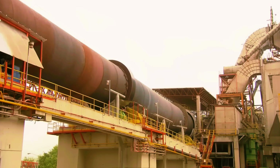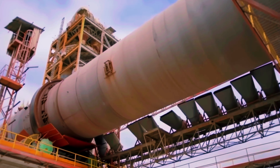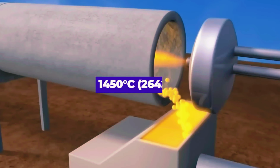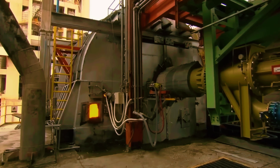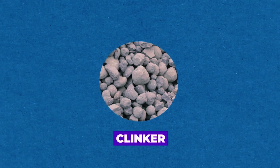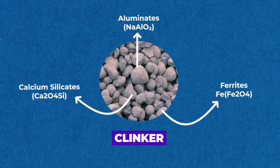The preheated and precalcined raw meal enters a rotary kiln, which is a long cylindrical furnace. The temperature in the kiln reaches around 1450 degrees Celsius or 2642 degrees Fahrenheit. In the kiln, the raw materials undergo a series of complex chemical reactions and sintering, resulting in the formation of small marble-sized nodules called clinker. The clinker consists of calcium silicates, aluminates, and ferrites.